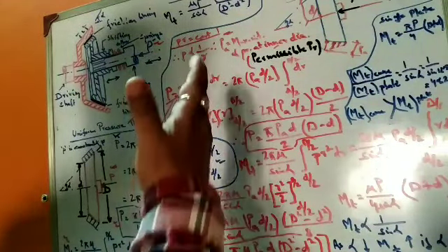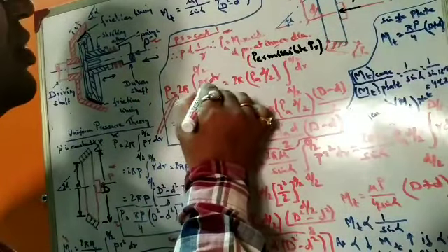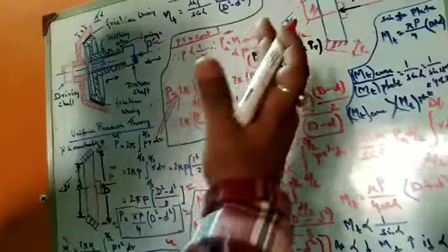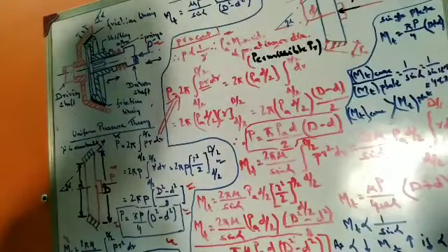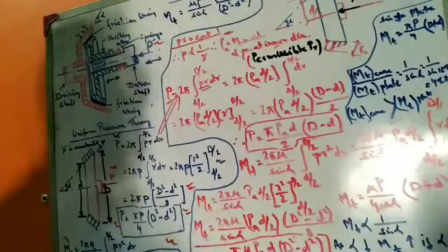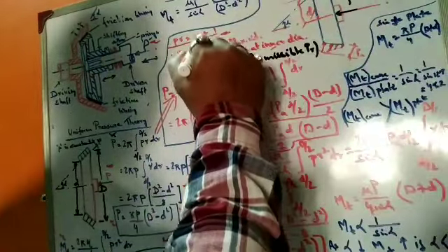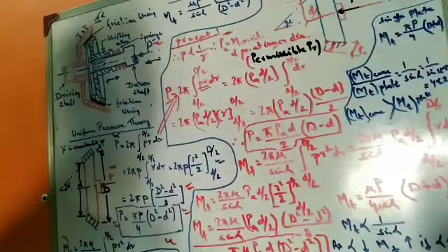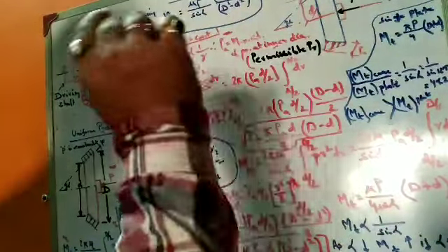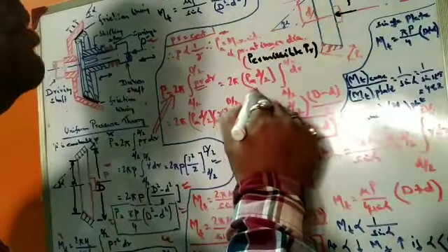Now you could see this constant PR remaining constant for uniform wear. So this quantity comes out. Now when this quantity comes out, we are taking the maximum pressure at the innermost diameter, because of the principle which I explained just before. P is inversely proportional to R, so when R is the least, pressure is maximum.